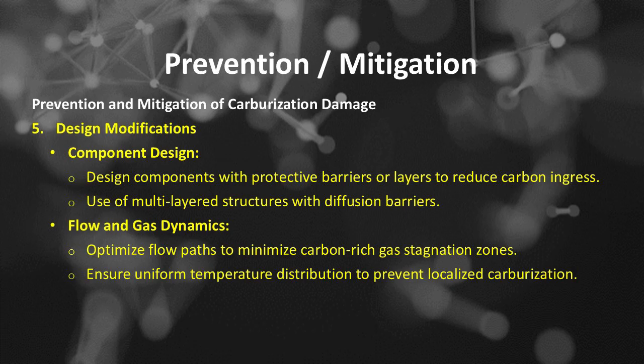Use of multi-layered structures with diffusion barriers. The second of design modifications is flow and gas dynamics. Optimize flow paths to minimize carbon-rich gas stagnation zones. Ensure uniform temperature distribution to prevent localized carburization.